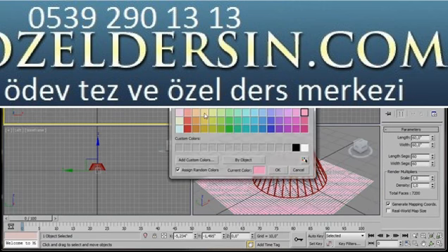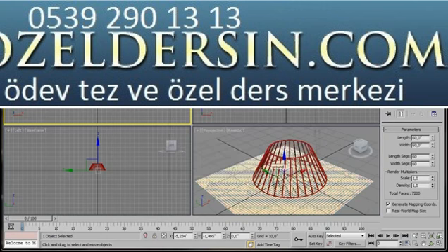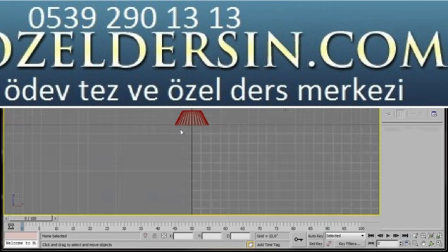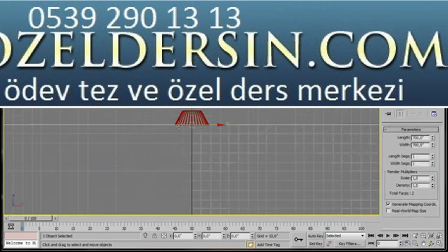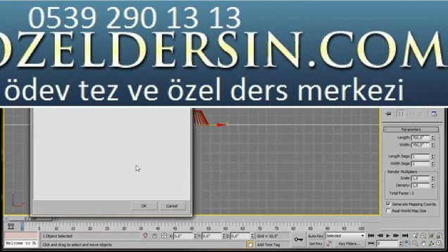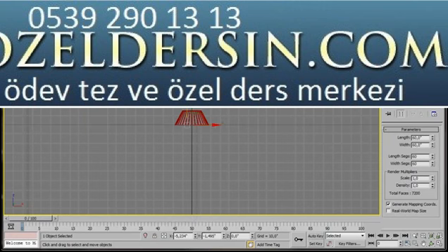Okay, now we can click anywhere in the front viewport to activate it. Then press Alt W to maximise the viewport. Select the plane. If we can't, we'll go to the main toolbar and click on Select by Name tool. And here in the dialog, select Lace Cloth, then press OK. Now we can drag our plane up.